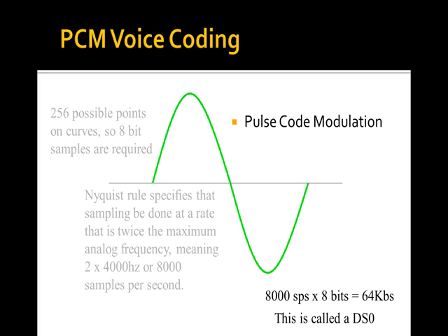Specifically, we're going to look at what is called the TDM, time division multiplexing hierarchy. You've probably heard it called the T1 hierarchy or T1 family. You may have heard it called the DS1 family. We'll get into all those terms a little bit. The very first level of that is what we do with an individual single voice line. And we talked about this a little bit the other day. I didn't actually dig into exactly what's going on. I take one voice signal, analog input.